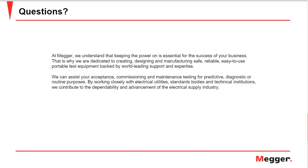Well, if the fault is inside of the zone of protection, the 87 has to operate. Because otherwise, how does the 87 differentiate? Whenever the fault happens between the CTs that define the zone of protection, the 87 has to operate, because it has no way to know whether the fault was inside the transformer or just outside the transformer, but on the wrong side, let's say, of the CTs.